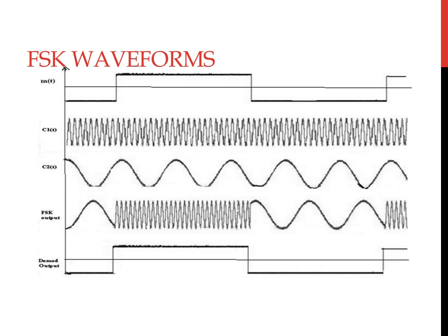So in the detection process we made use of the low pass filter, which eliminated the high frequency components and retained only the low frequency components. Then it was passed to the envelope detector and the comparator. So the demodulated output that you obtained is similar to that of the signal m of t, but it is a saturated value. So you obtain a peak to peak voltage close to 28 volts.